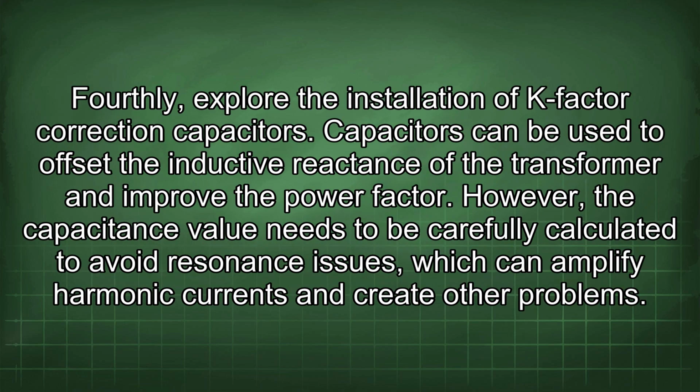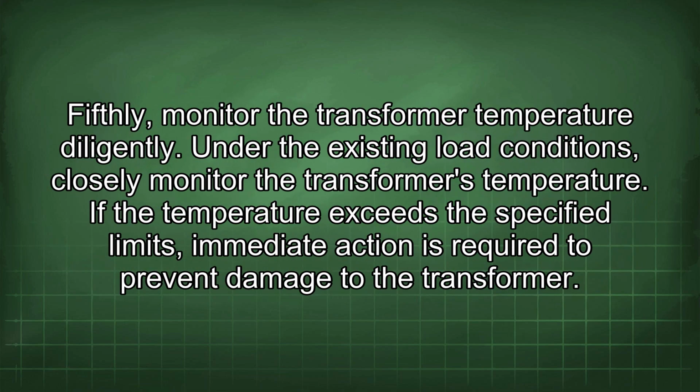Fourthly, explore the installation of K-factor correction capacitors. Capacitors can be used to offset the inductive reactance of the transformer and improve the power factor. However, the capacitance value needs to be carefully calculated to avoid resonance issues, which can amplify harmonic currents and create other problems.